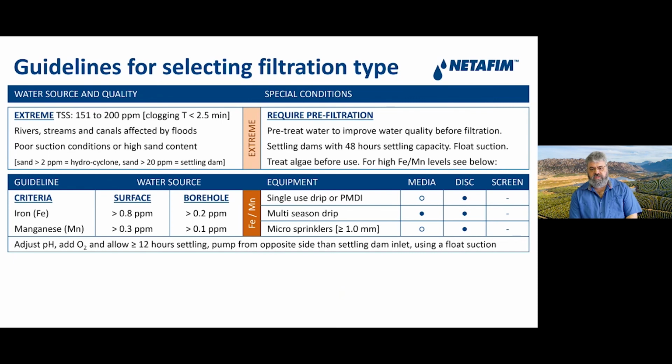If you look at the options now for filtration, you will see that it's either disc or media that we will use for this. And in this situation, the media filter will be your best option if you have iron, especially if you want to try and take care of the iron inline. That's not very common in South Africa, but it is possible. And the reason for the media filter is because of the slow velocity. You have a benefit in that application with the iron treatment.